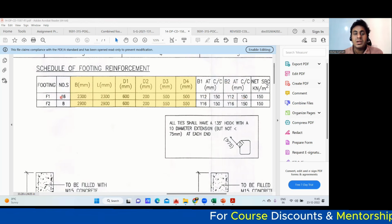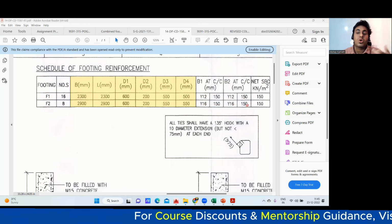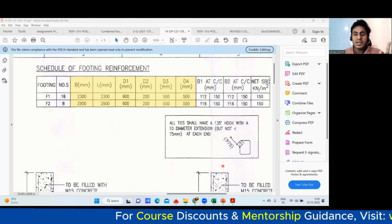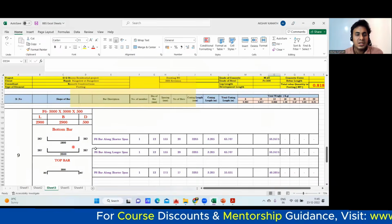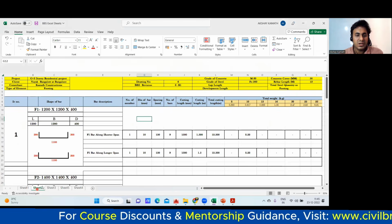For F1 footing, how many numbers are there? 16. F2, there are 8 numbers. You're supposed to use 16 diameter at 150 in the shorter span, and 16 diameter at 150 in the longer span. Pretty simple. If you want, I can do this for you. I'll go to the Excel sheet and let me take one footing. I'll take this particular footing. I'll do it here.